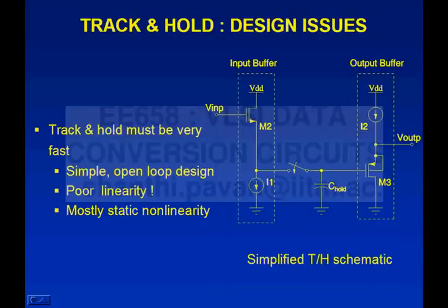In a flash converter, it becomes impractical to do anything based on op-amps, for the simple reason that the more the transistors, the slower your circuit becomes. And flash by definition you build only when you're trying to really push speed in that particular technology. So an op-amp based thing would not be practical in this situation. That's the motivation for doing this.